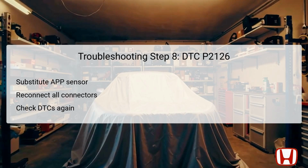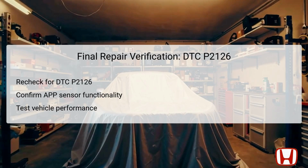If DTC P2126 does reappear, further investigation into the PCM may be needed. If, however, it does not reappear, the APP sensor is deemed functional, clearing the path for normal vehicle operation. Upon completing all troubleshooting steps for DTC P2126 and repairs, it is crucial to conduct a final verification of the repairs. The technician should recheck for the presence of DTC P2126 to assure that the issue has been fully resolved.